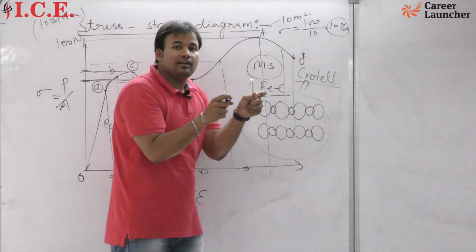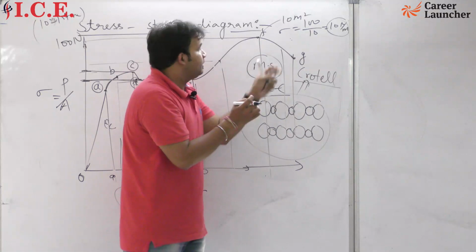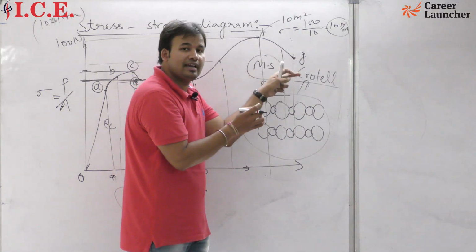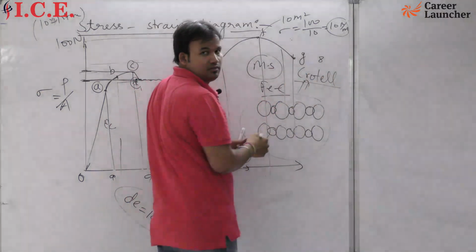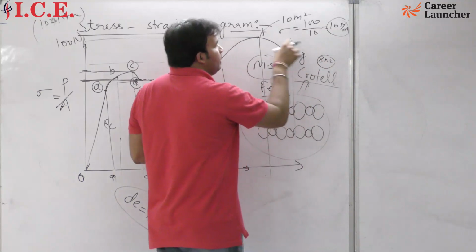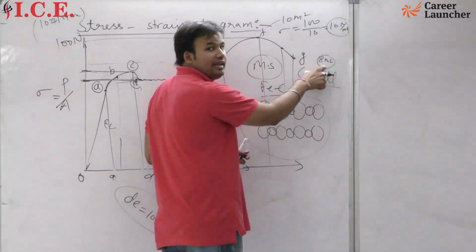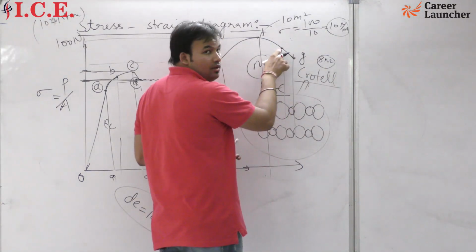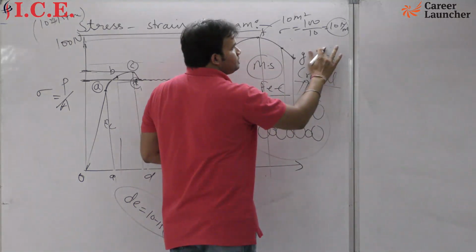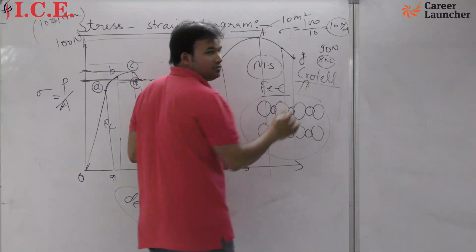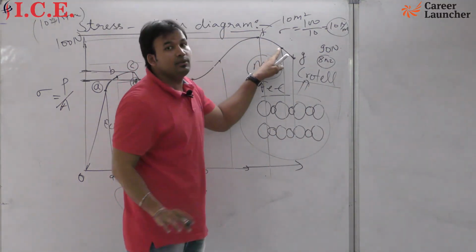So due to necking the diameter and area will become a little less. Suppose the area of the object becomes 8 meter square, where we assumed 10 meter square earlier, and accordingly we are applying a force of, you can say, 90 Newton. Are you getting me? Here 100 Newton, but for this point you are applying 90 Newton.